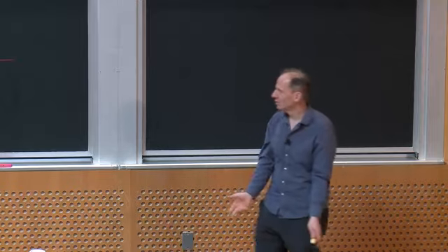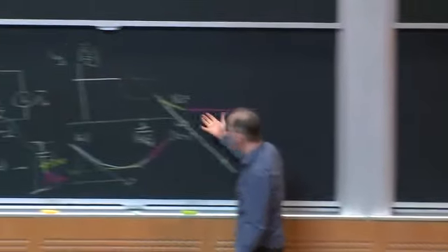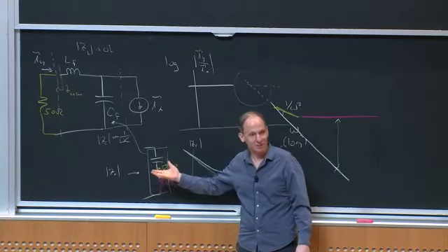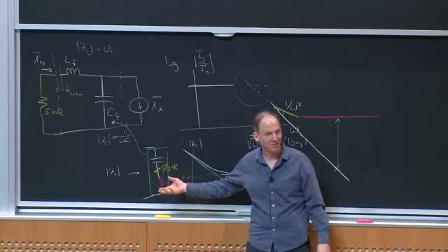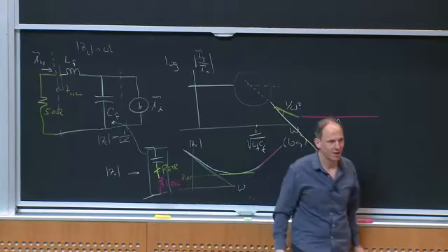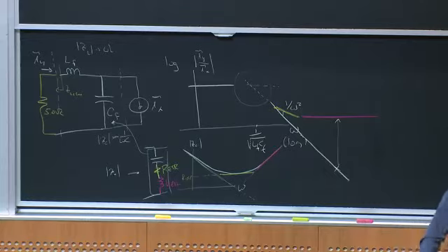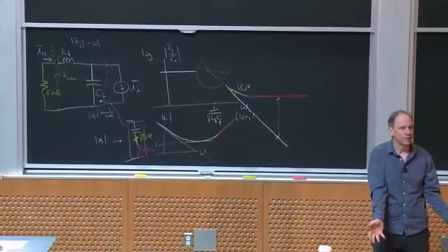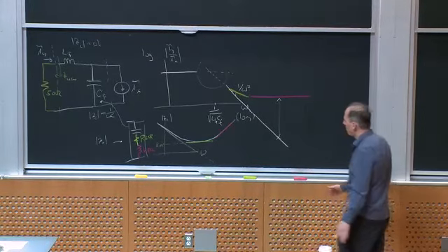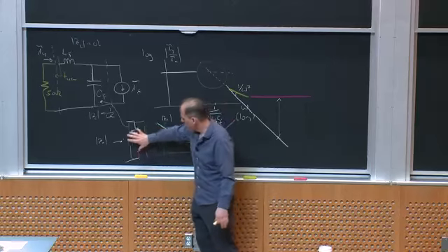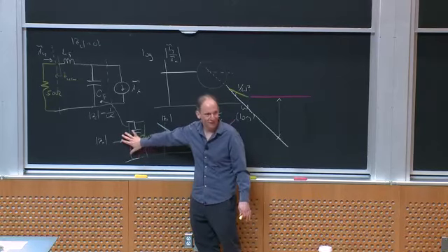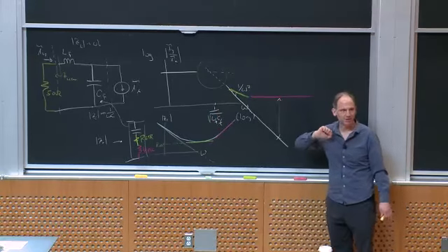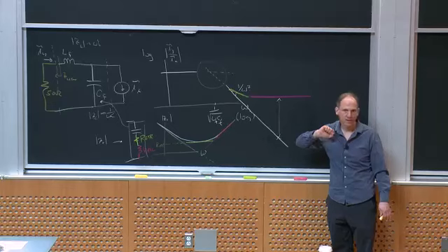Okay? Now, where does this kind of phenomenon happen? Well, it depends on the physical size of your capacitor, and on whether it's a good capacitor or not, et cetera. But very often, like 10 megahertz kind of frequencies is where these things are happening, as an example, or even 1 megahertz, depending on the size of the component. And that's right in the band that you're caring about and trying to attenuate. Okay? So these bad parasitics of the components, and usually the capacitors are the first thing to give out on you if you design the inductors right, will cause you to get a lot less attenuation out of this LC filter than you thought. Any questions about that?